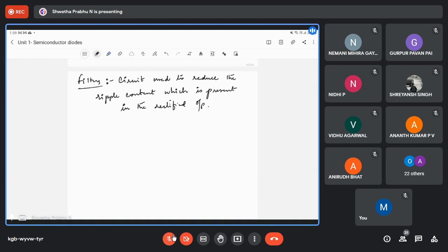Therefore, here in the syllabus we have full wave bridge rectifier with C filter. I have a question for you. C filter means capacitance filter, the rectifier built by using a capacitance filter. There are many different types of filters, say inductance filter, choke filters, RC filter, LC filter, RLC filters, C filter and all. So why are we choosing C filter? Why not any other filter?